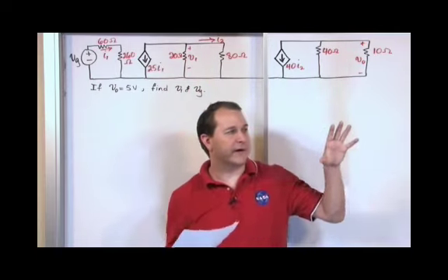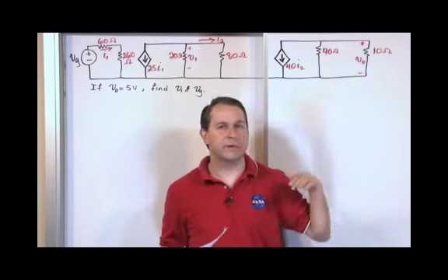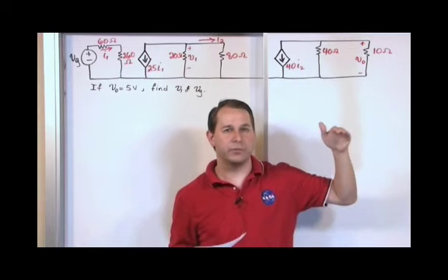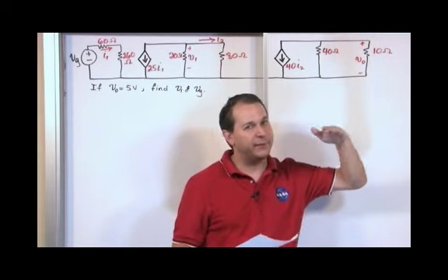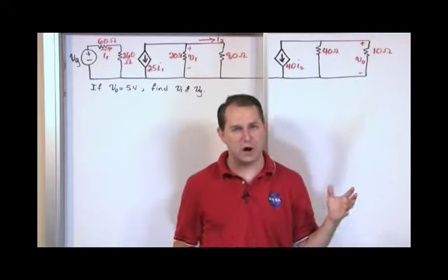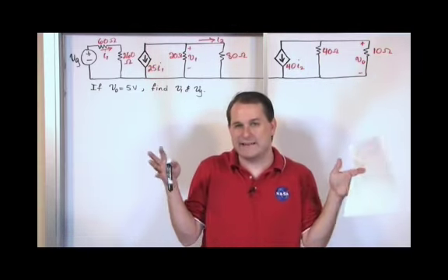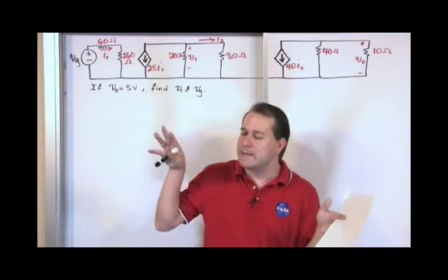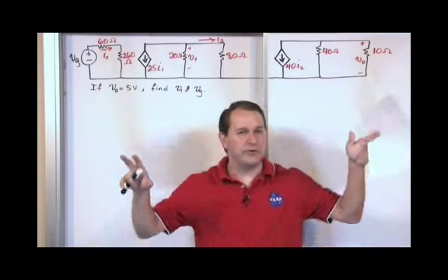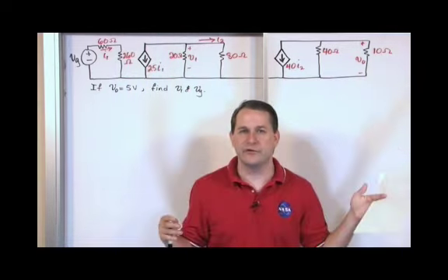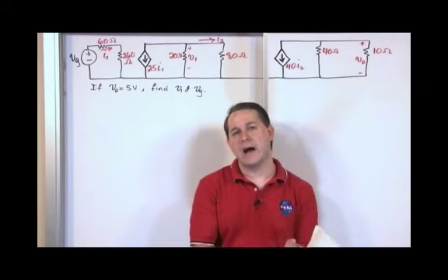If you have a very high voltage circuit over here that instead of 0 to 100 volts, maybe it's operating from 500 volts as a base voltage to 600 volts. The difference being still 100 volts, but maybe its base voltage is floated up, so to speak, is what we usually call it, up to a higher level. And then you have a circuit element over here in the same physical box as your guy, and he is operating properly from 0 volts to 100 volts. Well, then you've got two circuit elements, the base voltage of which are different. And so that can actually cause big-time electrical arcing. So I hope that analogy makes sense.